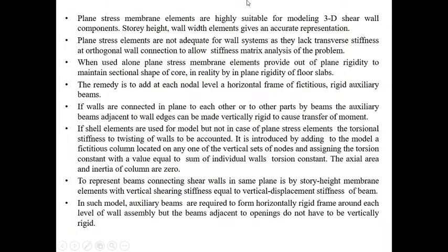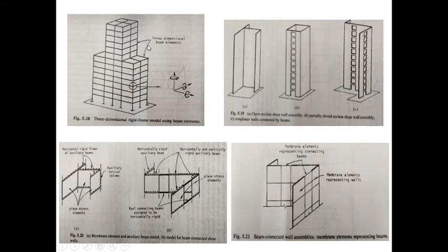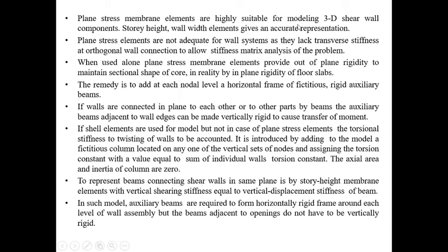Next, the plane stress membrane elements. They are highly suitable for modeling the 3D shear wall components. You can see here the plane stress membrane elements. The membrane elements can be used to represent the shear walls. Story height, wall width elements give the accurate or correct representation.